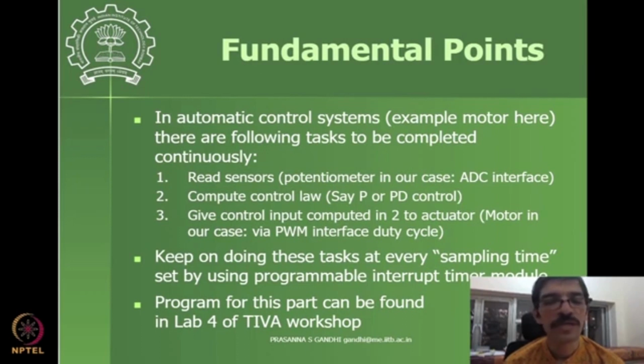You don't need to do any connections in your microcontroller. Like these modern microcontrollers, you don't need to do anything. It's only the software that you need to write, because these pins are already internally connected, so this pulse will get generated in the timer module and it will go on the interrupt pin.